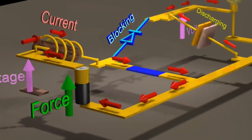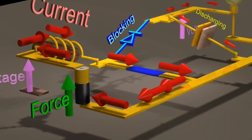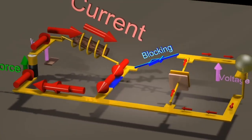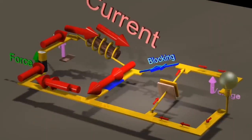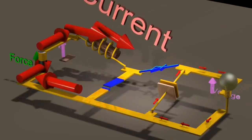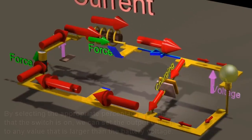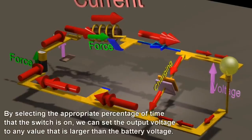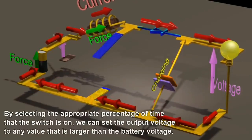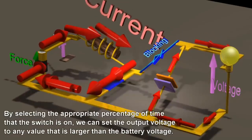If the switch is almost always on, then assuming we have ideal components, the current will theoretically keep increasing to infinity. During the brief moment when we turn the switch off, an infinite current would charge the capacitor to an infinite voltage. By selecting the appropriate percentage of time that the switch is on, we can set the output voltage to any value that is larger than the battery voltage.